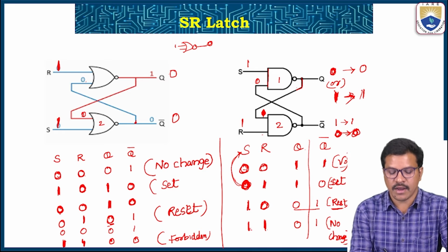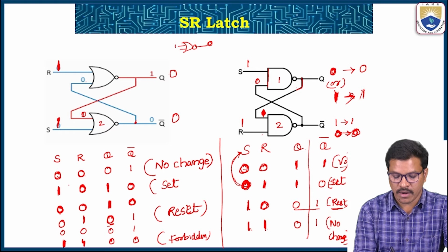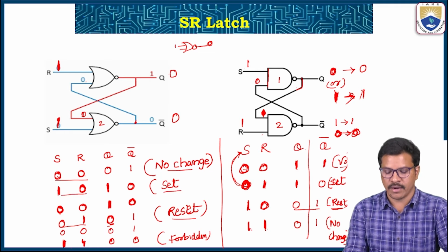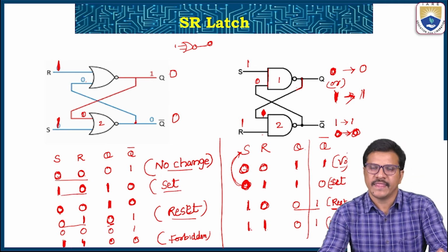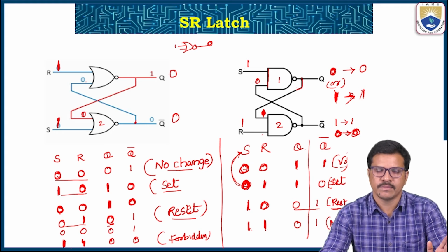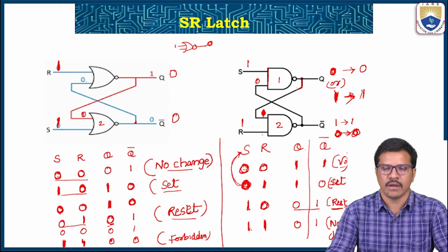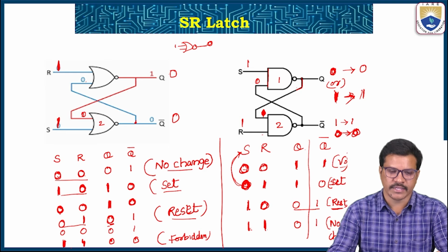In the NOR latch, easily remember: first case 0, 0, no change; 0, 1, reset; 1, 0, set; 1, 1, forbidden. Likewise, we can remember. This action is most important to understand how the latch acts as a memory element. Then we can easily modify this diagram for further topics like flip-flops, by adding extra circuits.